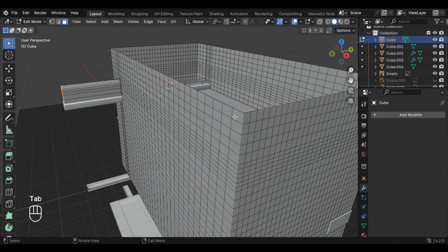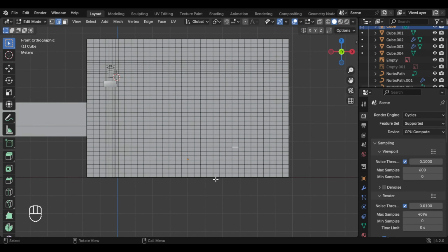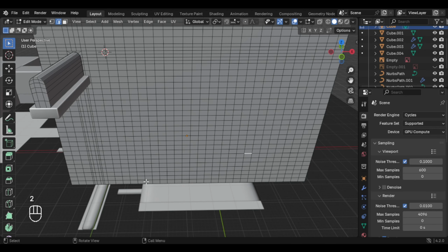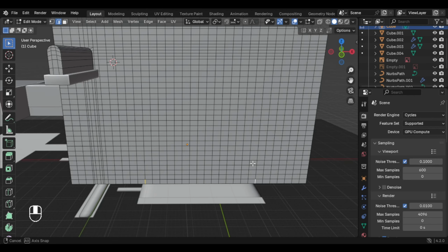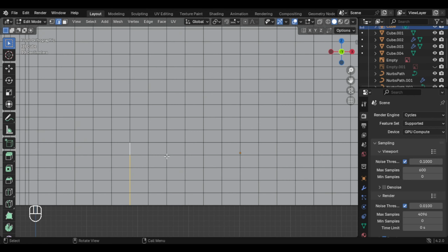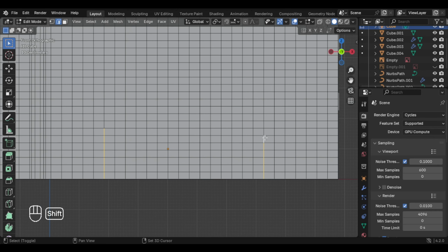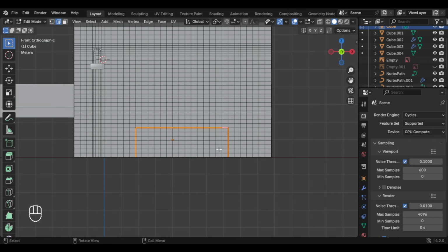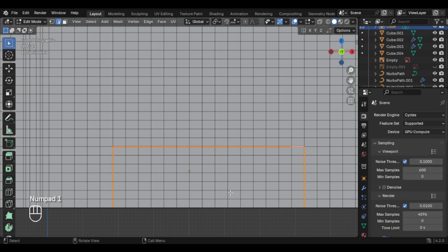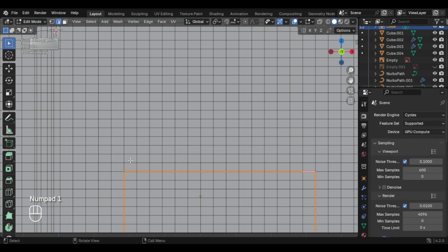So we can select our building and let's go to 1. And let's make these balconies and we can see where it is, so maybe here. And let's go to 1 and we can select a couple of edges. So maybe 7 and the height is enough, so we can just select 7. And we can select these ones and right click and Mark Seam. And also the other ones, so we can maybe make 2 in between. And do the same thing. So let's click one edge and Ctrl Shift the other one and right click and Mark Seam.